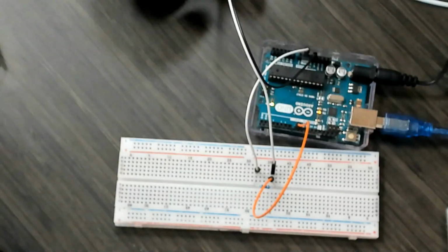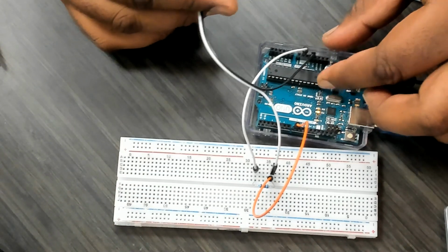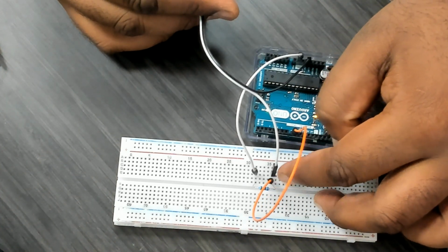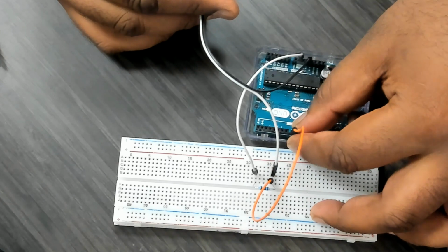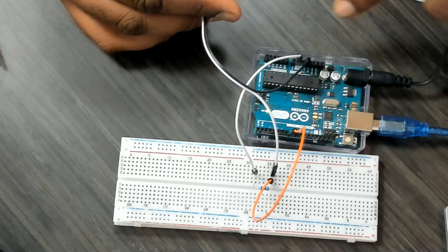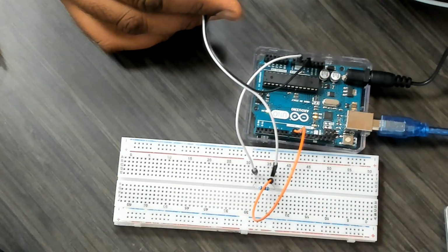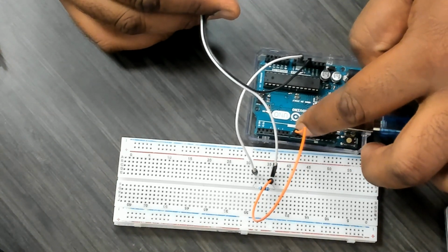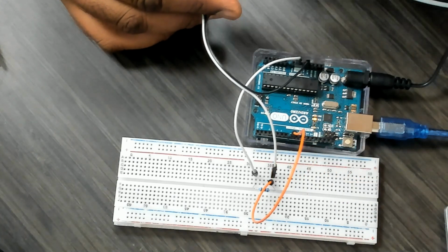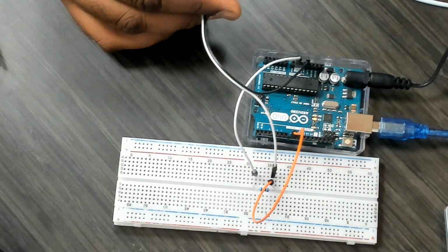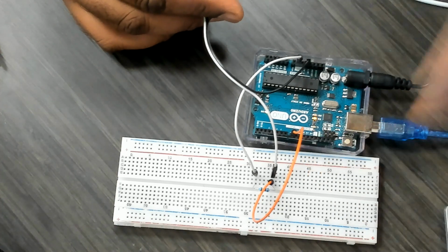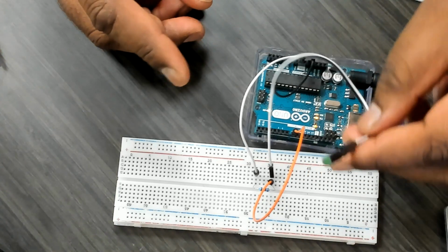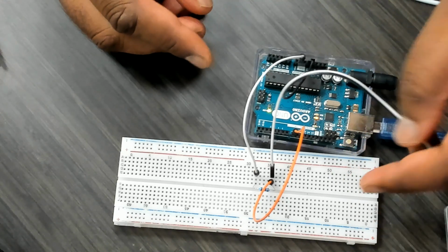If you see where I've connected this, this is the 5 volts and it is connected here. It is the other end which is connected to the pin. So technically I'm connecting the tilt switch to the pin. If this is connected, it'll provide 5 volts to pin 8. If this is open, then it is connected to 0 through a resistor, so 0 volts will be applied to pin 8. This is how you will design a circuit with something like this.